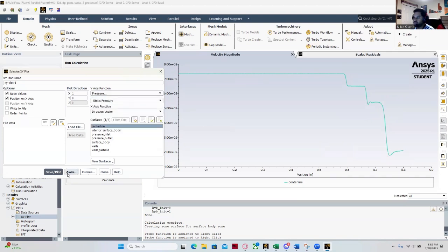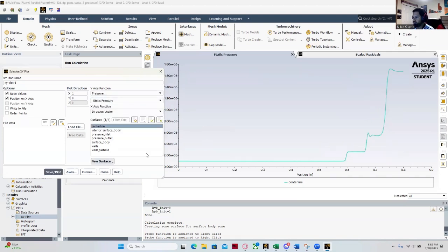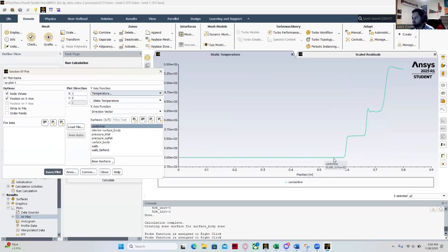And then we'll go to pressure. It'll have kind of like the opposite effect. Constant until the first oblique shock, pressure ratio is going to be greater than 1, so the recovery is going to increase. So then as it goes through the second oblique shock, it'll also increase, and then through the normal shock, the pressure increases. Same effect as temperature. You can see here, constant, first oblique shock increases. This is static, so this one changes, and then temperature increases after the second oblique shock, and then after the normal shock.